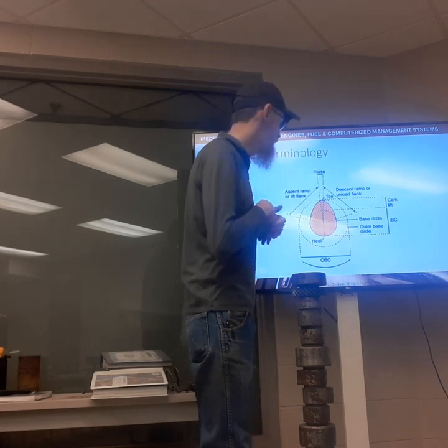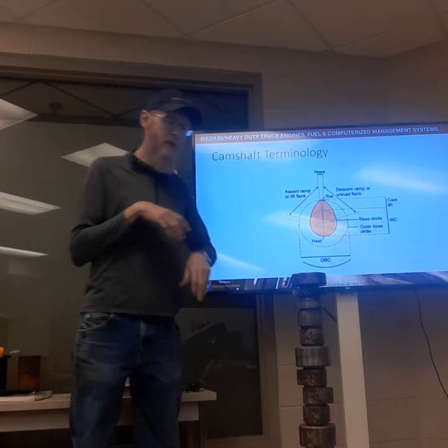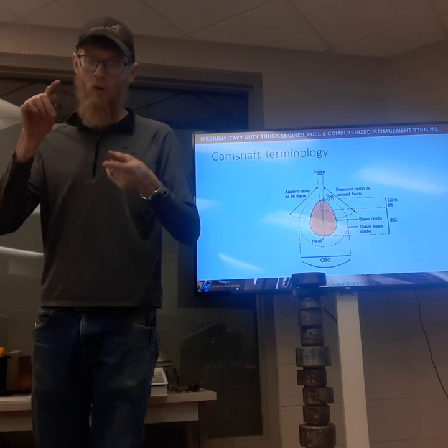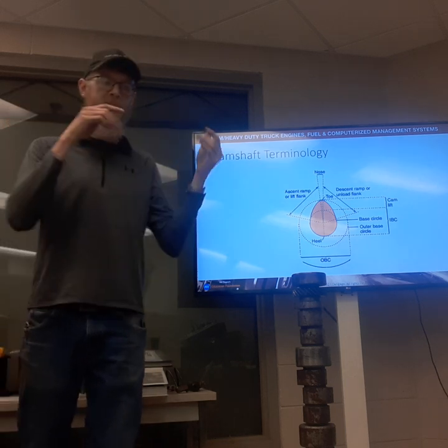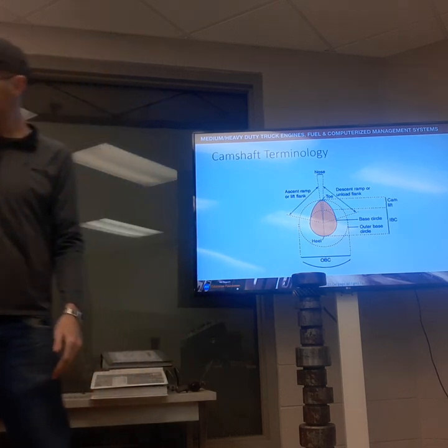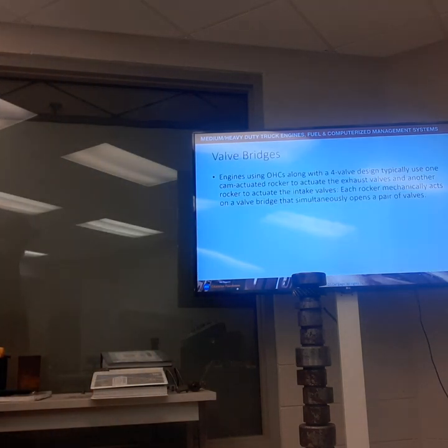the difference between the two is the valve lift, how far the valve is being opened by that cam lobe. So all the way back at the cam is where we control how long our intake and exhaust valves are open and how far they open, which greatly affects how much air we get in and out of the cylinder.